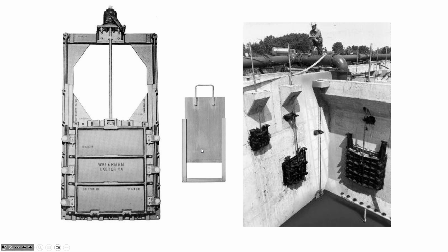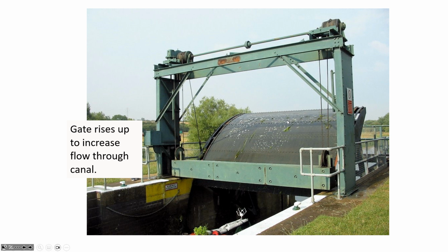So it's maybe the reverse of the storage tanks that you designed for your network, where you had a constant flow in but a variable flow out. Flow equalization basins at wastewater treatment plants have variable flows coming in, but they let out a constant flow rate. So there will be a lot of gates in situations like that where you may have storm water coming in from one direction and sanitary sewage coming in from another, and then you have to have different gates to open and close the flows out of the flow equalization basin.